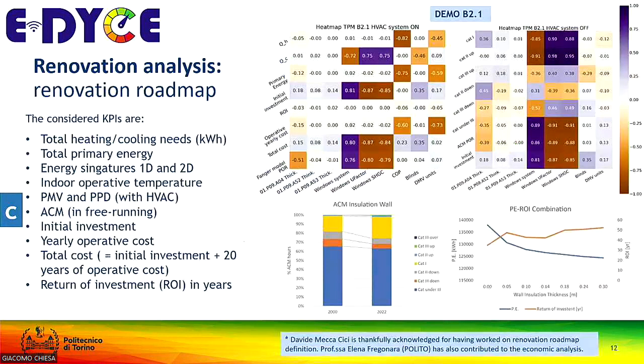To go very fast, the tool itself and the analysis also support the possibility to do a parametric or sensitivity-based approach from the retrofit point of view. So it's not only generating 5, 3, 4, or 6 scenarios of variation in the heating, the cooling system, the ventilation, the shading, and so on, but there is the possibility to vary these with ranges, so different thickness of insulation, different position of windows, and so on, and to connect to them, where possible, also cost analysis, using regional or national databases of costs, or build your own.